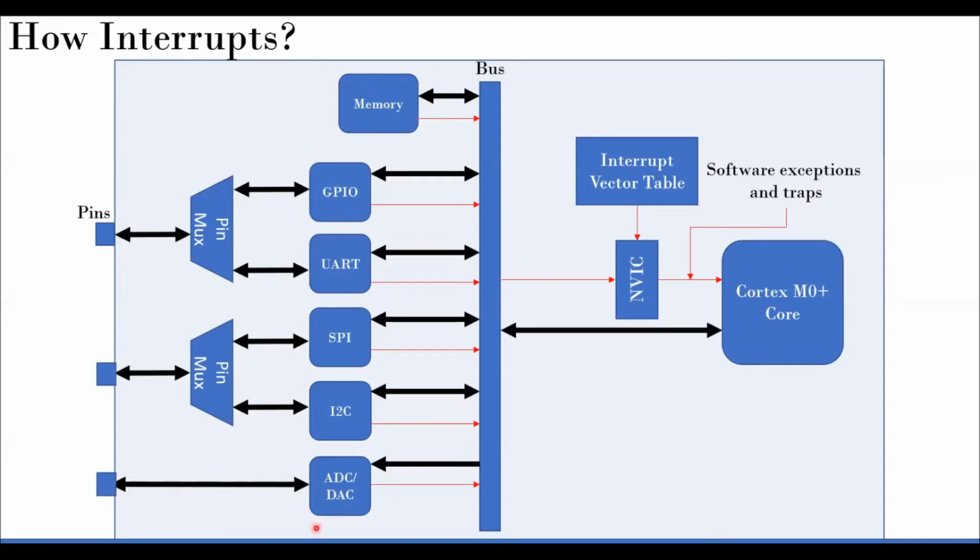And all these peripheral devices are basically individual configurable controllers. For the GPIO controller, we discussed the whole set of registers: the output registers, the direction register, the input register, all those. Similarly, other peripherals also have their own registers associated with them, right? Those registers are again something like a memory location, memory mapped for the microprocessor, and they are connected through the bus to the core.